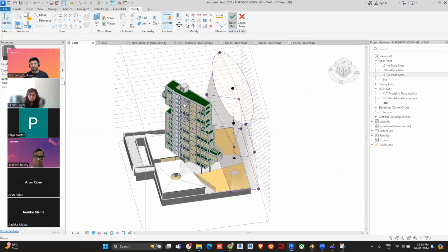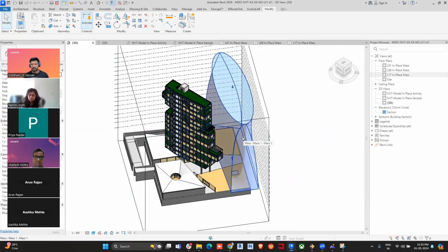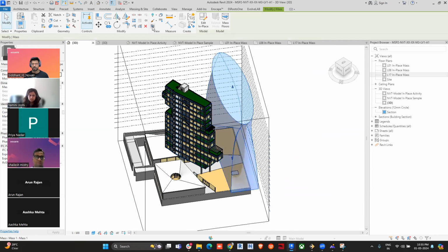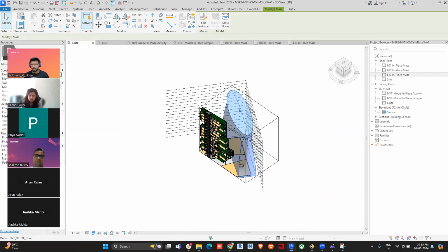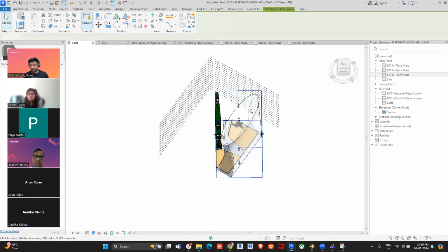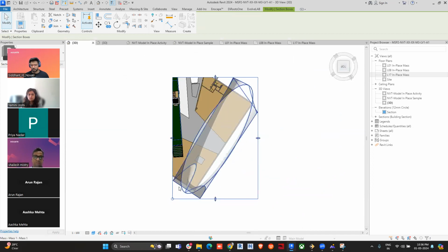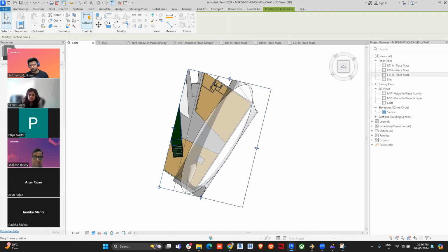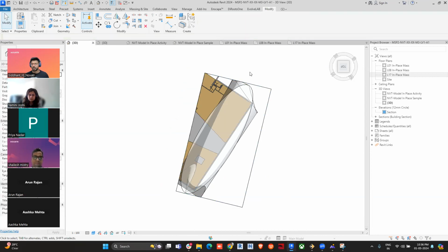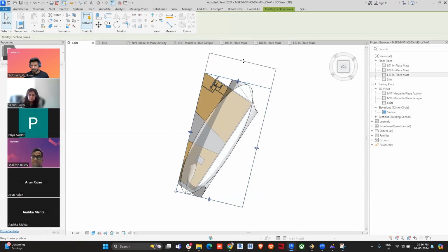I think this building is kind of obstructing my view, so what I'm going to do now is select this element and use this tool, section box, or you can say selection box. It will just consider our building only, but it's tilted, so I'll go to top and rotate it. Here there is an option to rotate. This section box is just for visual purposes. You can play around with it afterwards. So we have our massing inside our box. Let's just extend these elements as well.